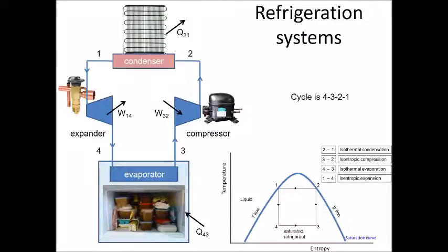And the condenser, well, the condenser is the back of the fridge, isn't it? It's that black radiator where we are rejecting heat at constant temperature. And have a look at the TS diagram to convince yourself that you understand what's going on. So it's the condensation process in our reverse Carnot cycle. So the heat is being dumped out of the back of the fridge or freezer into the ambient environment, and